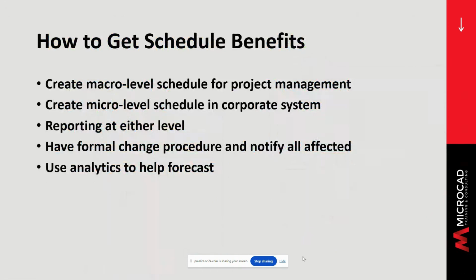The implementation of scheduling links the scheduled tasks to objects in the BIM model. The tasks also connect to the costing structure. If you are maintaining a micro-level schedule in another app, the project management schedule is mapped to summary nodes of the detailed schedule. In the very early stages of the project, change is to be expected and should be made easy. At that stage, consensus and commitment are important. Later on, the change process has to be formalized and should only happen after full analysis. The analytics available should be used to predict the impact of the change and to report where the project is versus plan.